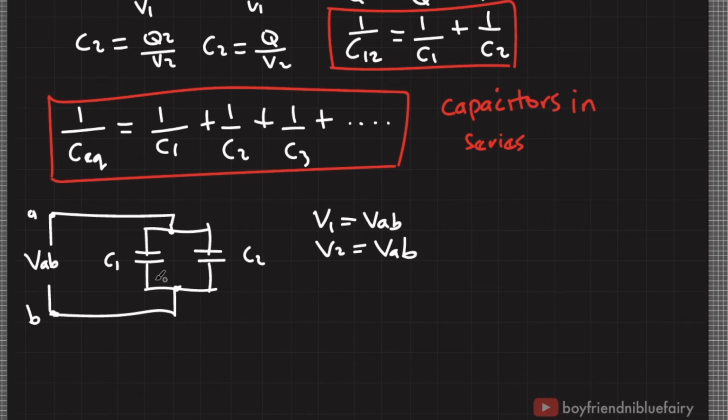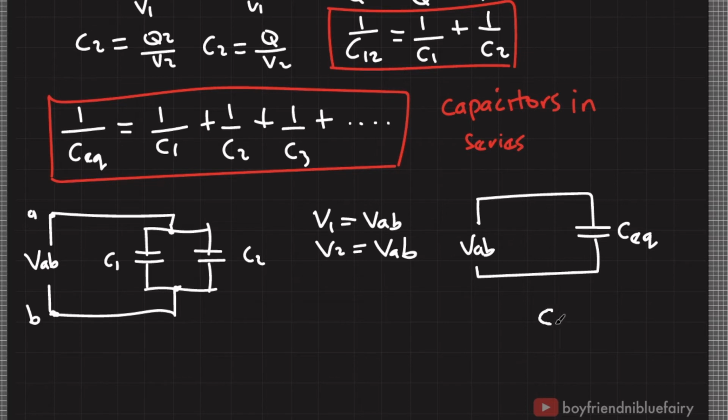In circuit analysis, calculating the equivalent capacitance of two capacitors makes the calculations easier. So we would like to get the equivalent capacitance of these two capacitors in such a way that we could represent it with Q over V sub AB. When electronic components are in parallel connection, notice that when current flows here at this node, the charges are divided into two.